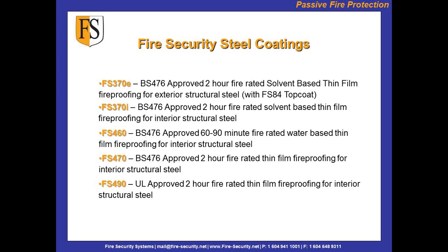It doesn't require, all indoor coatings don't require a top coat, because there's no moisture content that's going to get to them. There's no water. Usually if they're not hidden behind a wall and they are shown on the steelwork, they will be coloured. But that can be just the standard interior paint, commercial paint, latex or acrylic. There's no issue.